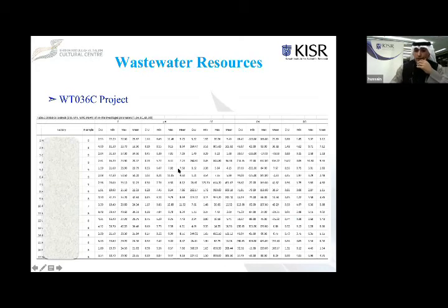That's a sample of the information we collected with respect to the field measurements, including temperature, pH, conductivity, and dissolved oxygen. We also have other parameters that we investigate according to the Kuwait EPA regulations, to see what criteria of water need to be reached.